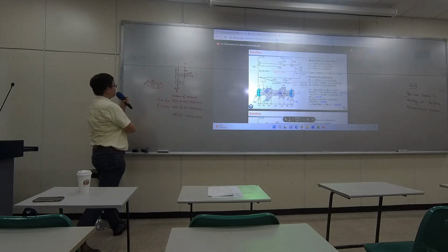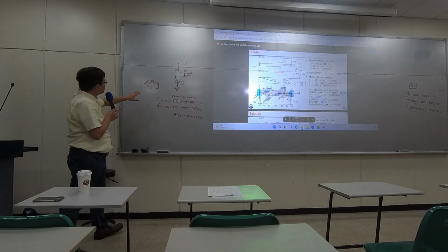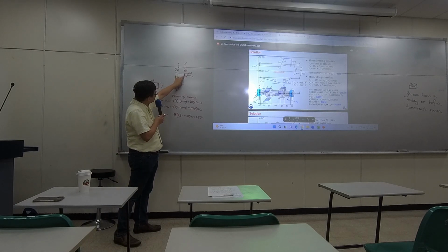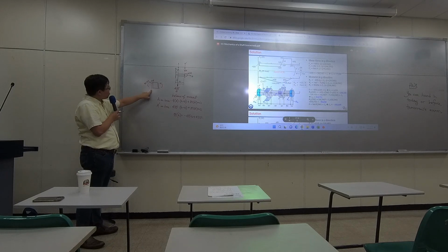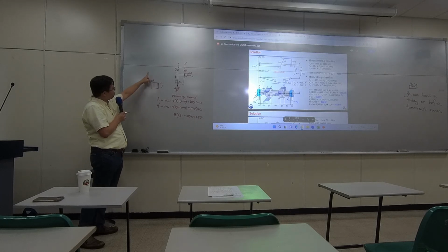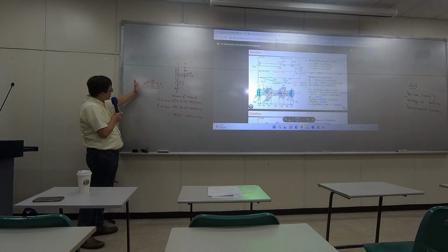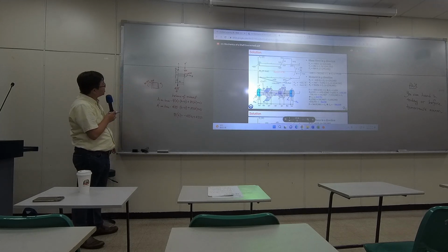Yes. Based on the orientation that we made in the past, if you take a tiny element right here, we would like to name our shear force on the left as positive for going up, and we would like to indicate our moment on the left as positive going clockwise.